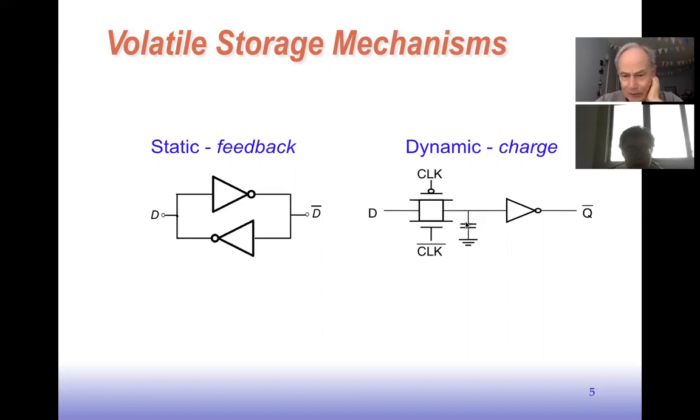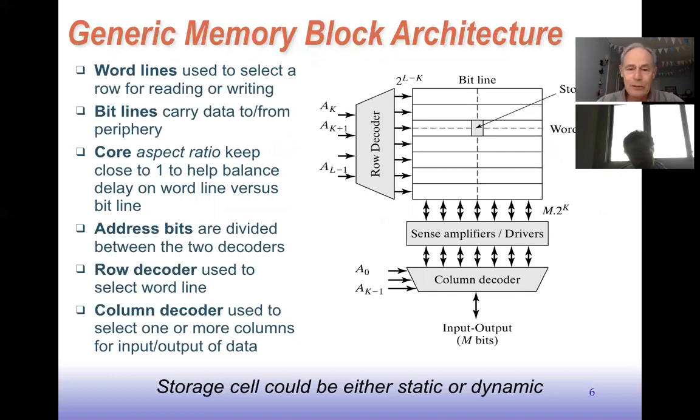It's much smaller, fewer number of transistors, as we'll see when we look at the DRAM circuits, and therefore it's hard to get it right, but it's so dense and so cheap to build memory this way that we have DRAM circuits that can be made robust. And I'll talk about what we do to make them more robust later. Okay, so those are the cells.